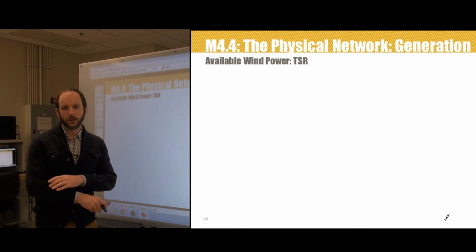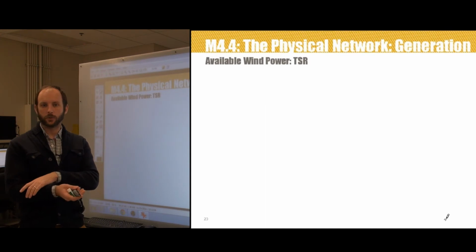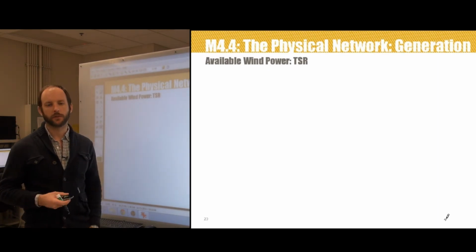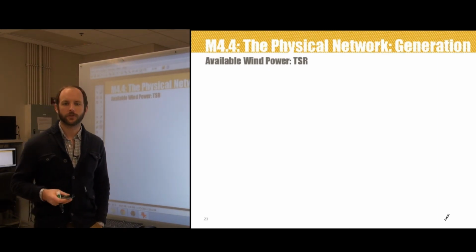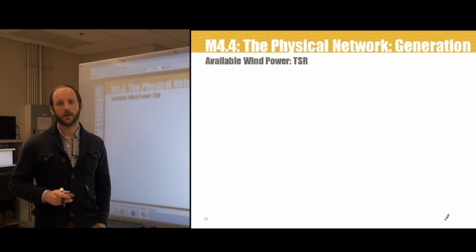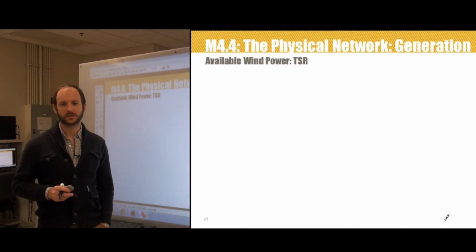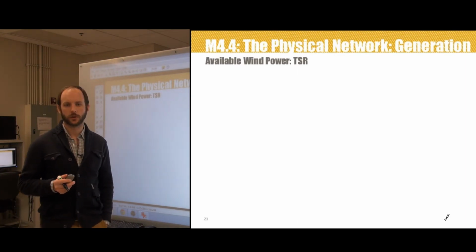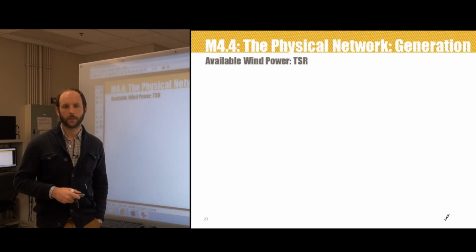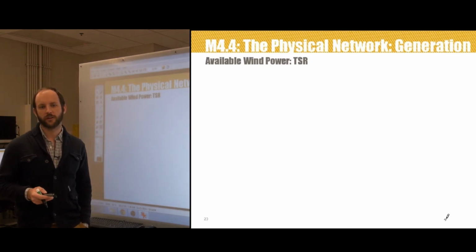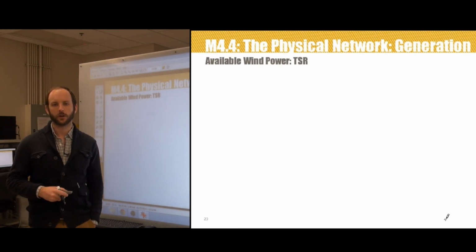Although the theoretical upper limit of a wind turbine is about 60% of the power contained in the wind, modern turbines under best operating conditions only approach about 80% of this limit, which makes them overall 40 to 50% efficient at converting wind power into rotational power. For a given wind speed, rotor efficiency is a function of the rate at which the rotor turns. Rotors that turn too slowly let too much wind pass by and efficiency drops. Rotors that turn too fast cause blade turbulence that increasingly affects the following blades and decreases overall efficiency.